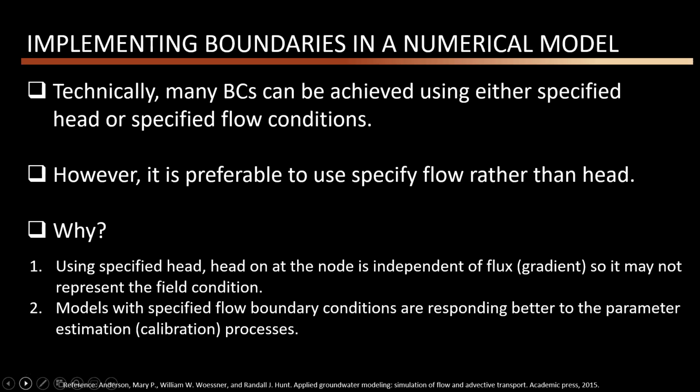Groundwater modelers use specified head and specified flow boundary conditions a lot in their models, but it is very important to know that technically most of the hydraulic or hydrological processes that we are concerned with in groundwater modeling can be simulated using either specified head or specified flow boundary conditions. But we usually prefer to define boundary conditions using the specified flow concept rather than a specified head concept.